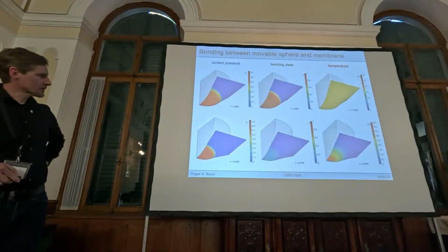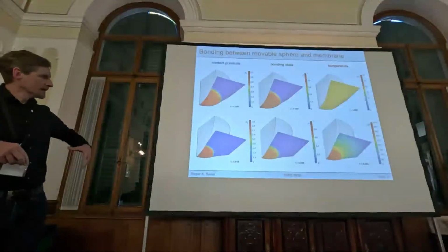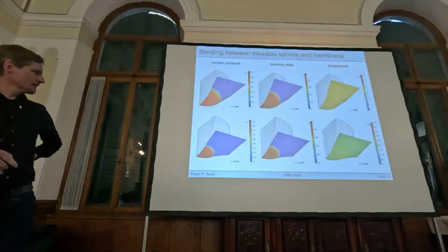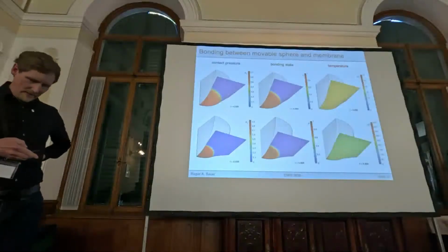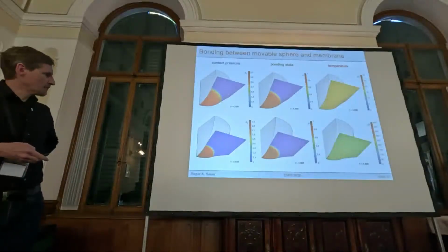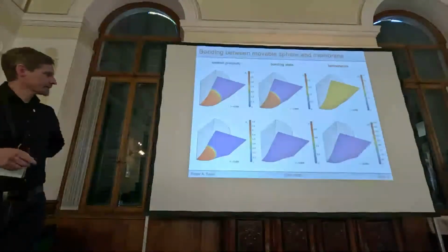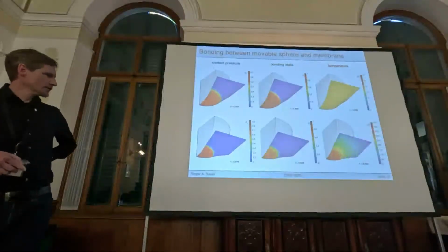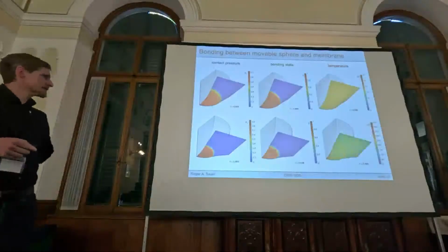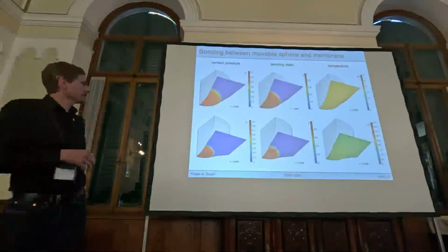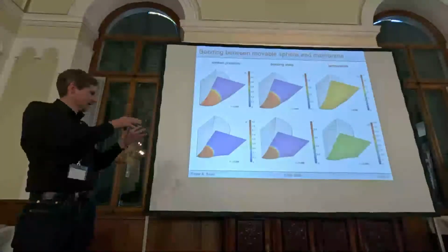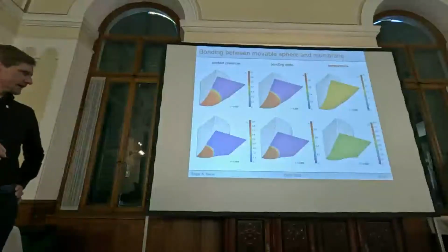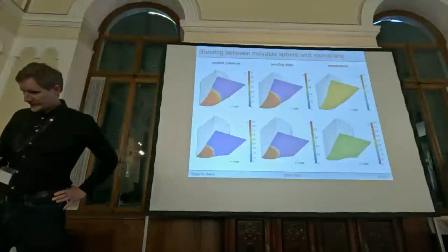As temperature develops, the stiffness is increasing, and therefore the sphere is moving upward. In this case, I have to admit the temperature increase has to be very large to see large motion. But that's also good because this is, in some sense, verifying the implementation, that it can handle large temperature changes and large deformations.